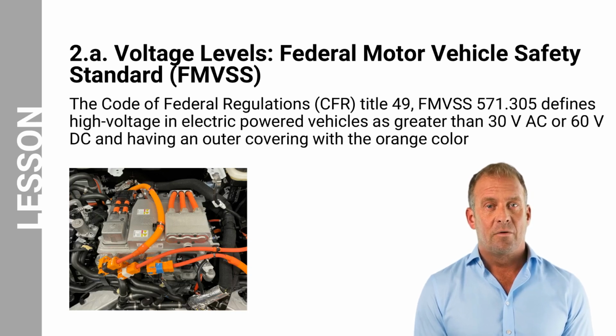The Code of Federal Regulations, Title 49, Federal Motor Vehicle Safety Standard 571.305 defines high voltage in electric-powered vehicles as greater than 30 volts AC or 60 volts DC and having an outer covering with the orange color.